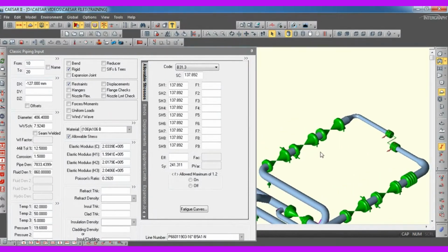Today we are going to check the flange. We are going to see the flange leakage check for the flanges. Generally, flange leakage will be checked based on the criteria given in the stress design basis. In some stress design basis, they will give some criteria, like for 24-inch lines and 900 rating flanges only we need to check the flange leakage. That is maybe in onshore.